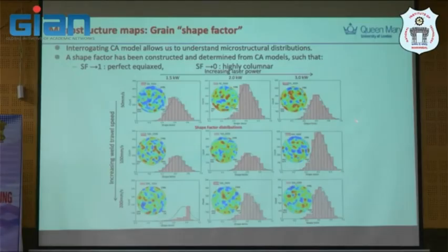And in addition to that, we can also predict texture as well. Textures. I think you understand texture is orientation based. I mean, compared with the growth orientation of the material investigated. So in this case, we predict beta grain. Beta is the body centered cubic crystal. So I'm sorry, it is too material now.